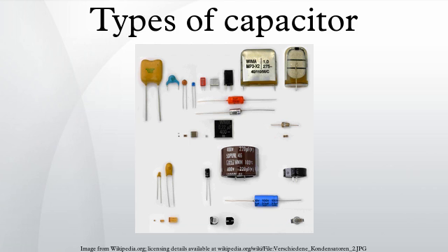Parasitic inductance is further lowered by placing the electrodes on the longitudinal side of the chip instead of the lateral side. The face-down construction associated with multi-anode technology in tantalum electrolytic capacitors further reduces ESL. Capacitor families such as the so-called MOS capacitor or silicon capacitors offer solutions when capacitors at frequencies up to the GHz range are needed. Inductance and self-resonant frequency: ESL in industrial capacitors is mainly caused by the leads and internal connections used to connect the capacitor plates to the outside world.